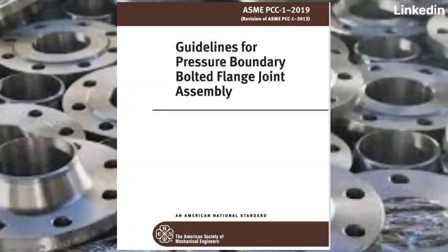Would you want to answer this? Ramakrishna, you want to answer something? No, actually, I didn't come across this issue. Himanshu, what exactly is this 44(b) and PCC-1 problem? So your flange is failing in the PCC calculation. Yeah, it is failing in PCC-1 Appendix O, the standard flange.